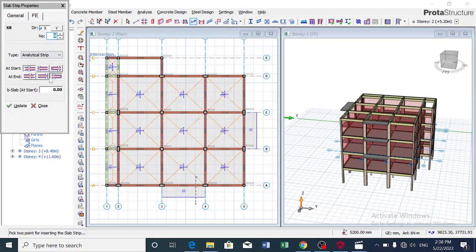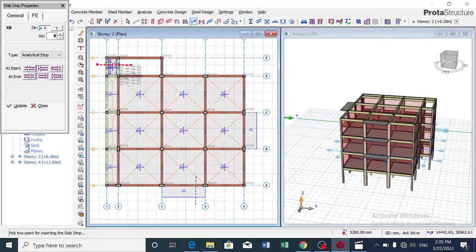Now in our X direction, I click on discontinuous end, which can also be the outer end to outer end. So I click here, I drag and I hold my control to give me a straight line. I click again. For this, it starts with an outer end, and this end is also an outer end. So start and end with an outer end. So I continue, I hold here, click, drag, hold my control key, I click again.